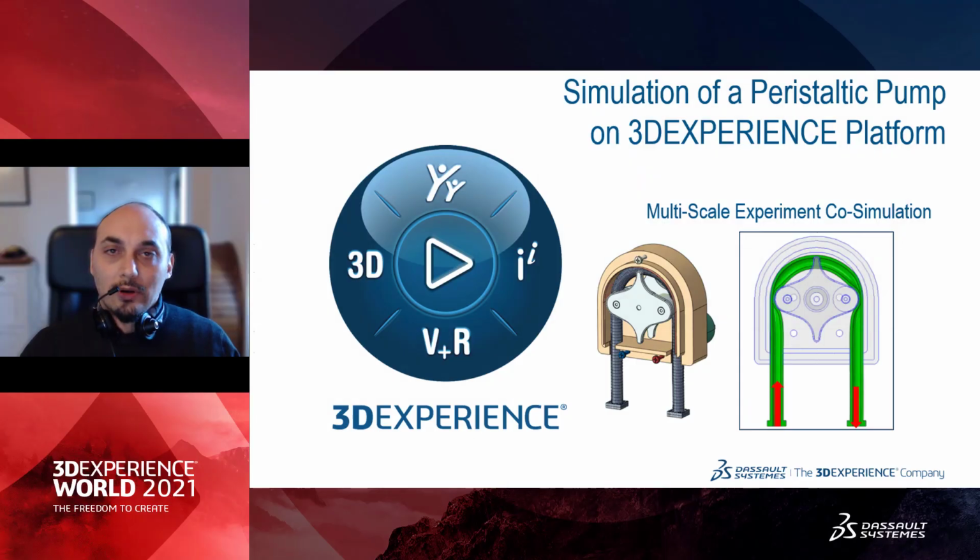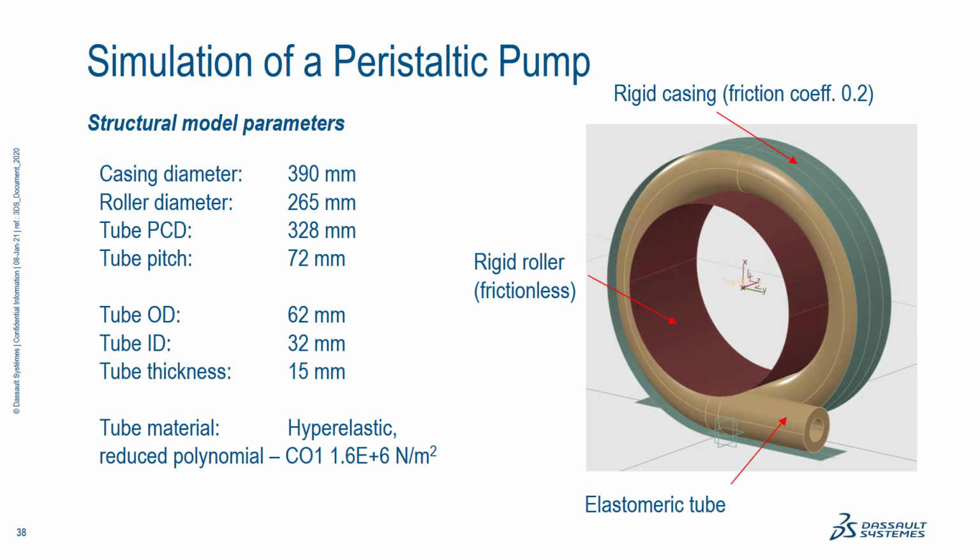Now let's have a look at an example about a peristaltic pump on the 3DEXPERIENCE platform. Here we have the simulation of a peristaltic pump. This is the structural model. You can see a casing with a roller inside. The roller, the rigid roller, is frictionless, and we have an elastomeric tube with a hyperelastic material. So we have something that will move and deform the tube in order to create a fluid dynamics behavior.